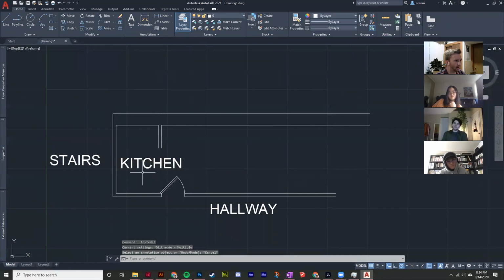And then also show you scale. Scale is another one in the modify tab. So I can click on that. It's like move or rotate. You have to select the object, hit enter, base point right there, and then you can either do it, again, visually, like with the rectangle, or you can specify a scale factor. So if you wanted it to be half as big, you enter 0.5, excuse me, and it'll shrink it down